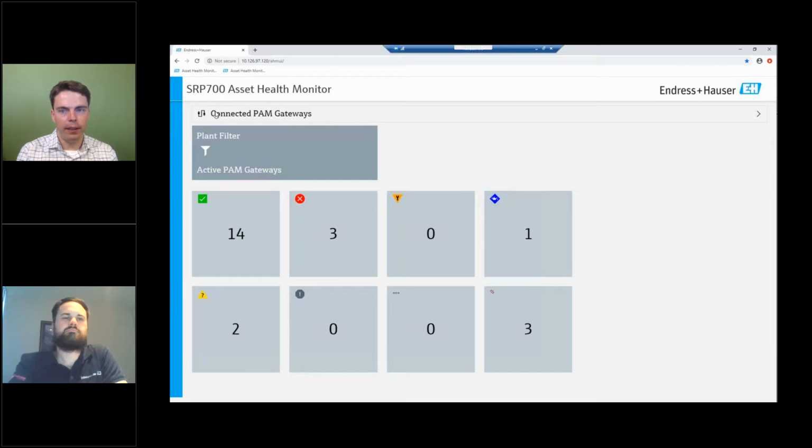And we can also integrate that. Let's say, take a Rockwell system with FactoryTalk View, that's a client solution where you can have a server and virtual machines, and then you can restrict the access to those machines using that security. So we have a demo system in the US where you need an RFID card before you're able to see that web page. So we have basic security implemented in that system here, but everything that's more advanced, as usual, you leave to professional providers, and then we'd be utilizing their systems. So yes, we can restrict the access to those pages, and we can implement that also in a security concept.